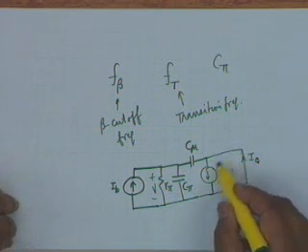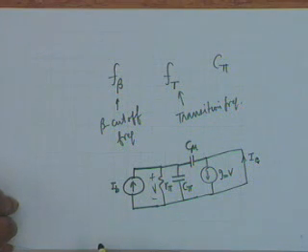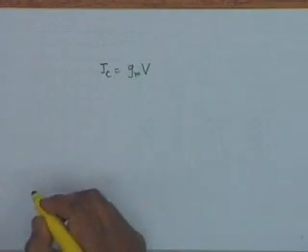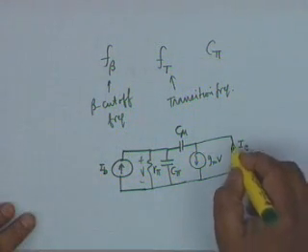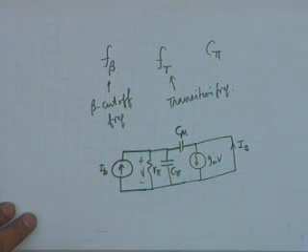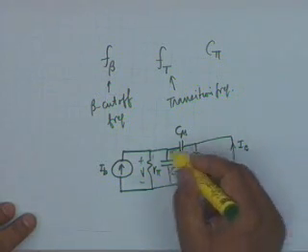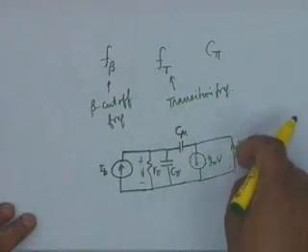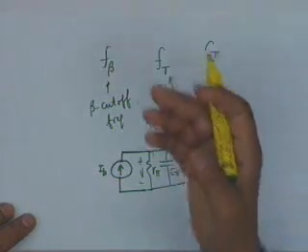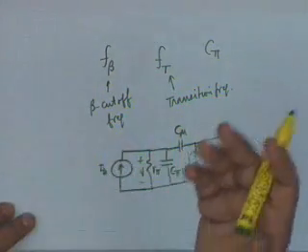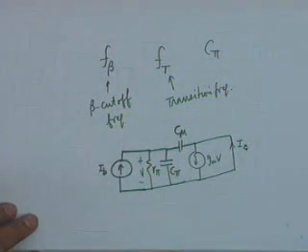If I calculate this, obviously I sub C is equal to GMV. Isn't that right? I sub C is not equal to GMV? It's a short circuit, and therefore the current generator, why should it send the current through impedances? It finds a short circuit, so it sends all its current here. There is no approximation here, this is exact. The current generator also looks for the shortest possible path, like every system in the world goes to its lowest potential energy. Why should the current generator be obliged to send the current to C mu? It doesn't. It sends all its current through the short circuit. So I sub C is GMV.